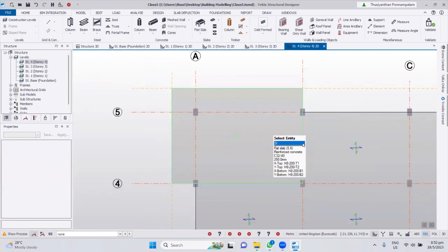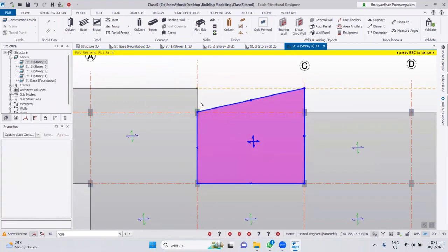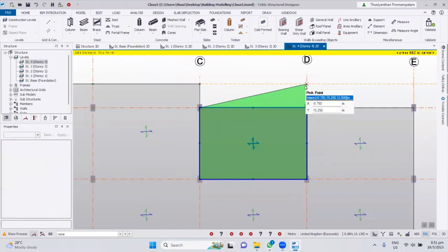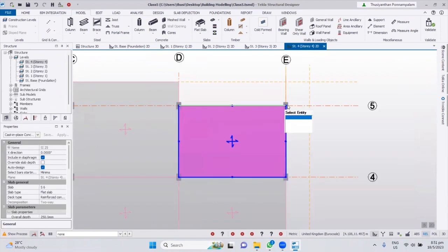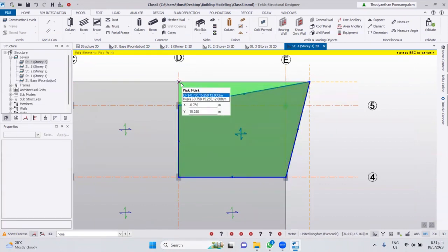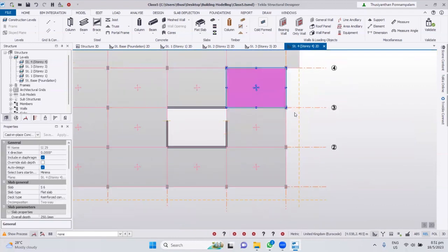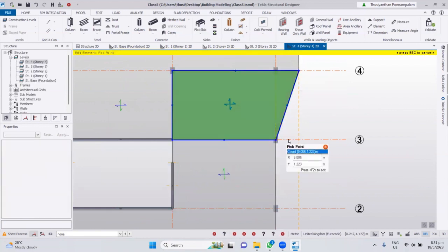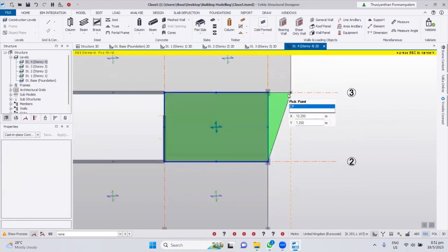In a similar way you can modify all the slabs. So let me finish the slab first. Later we can go on to model the drop panel. If you want, you can just draw one panel, then extend it, but to me that is not a good idea.